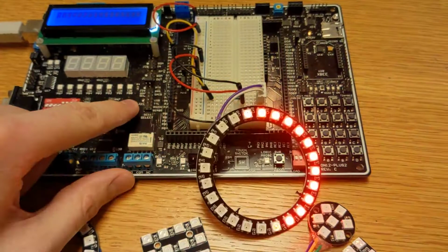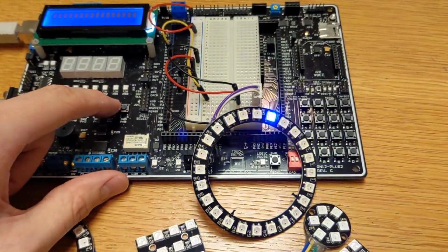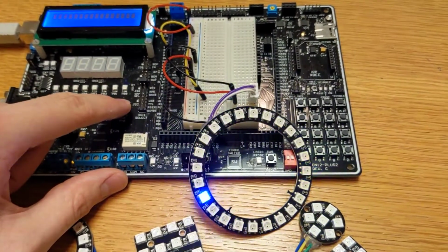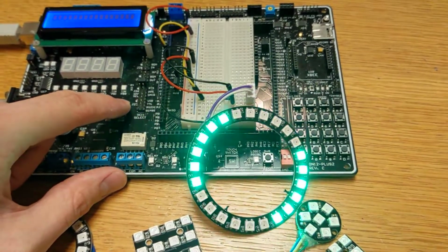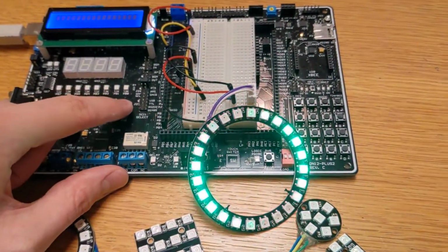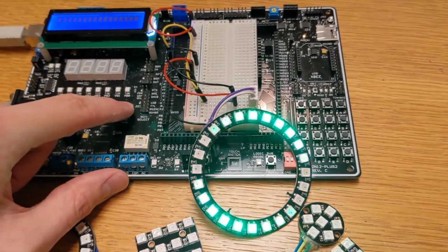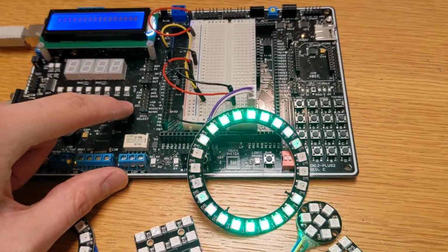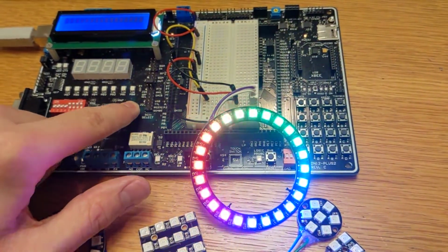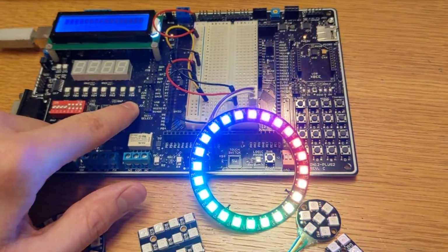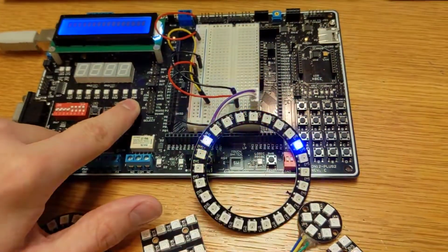So I've got these different animations. This one's interesting because I use a pseudo-random number generator to pick a random pixel to light up. This one's interesting because I use a sine lookup table to get this pulsing effect that you see. Off, and then this is a basic color wheel, and this one's more blended. So I can go left or right in the animation sequence.